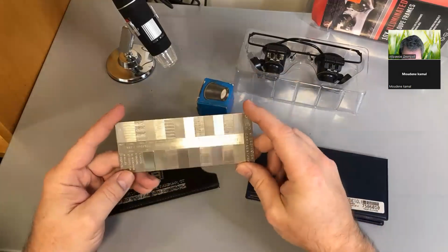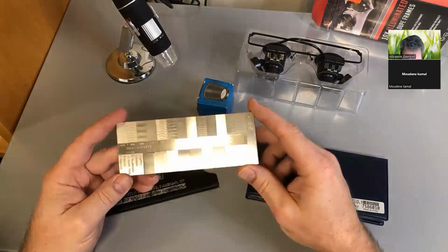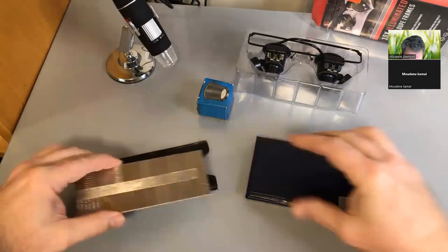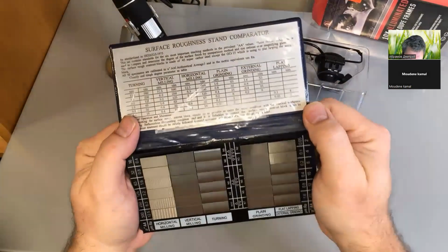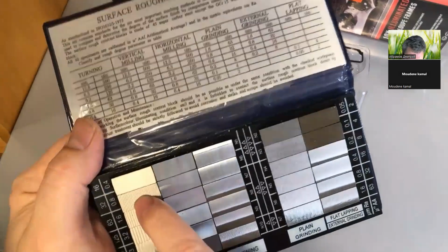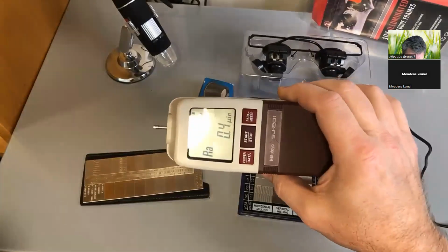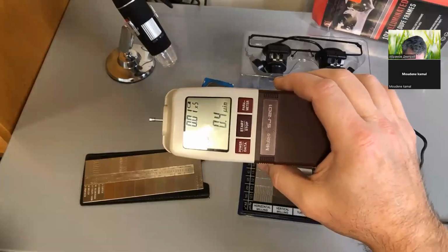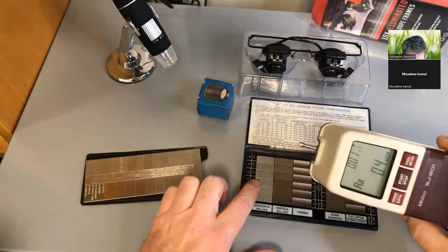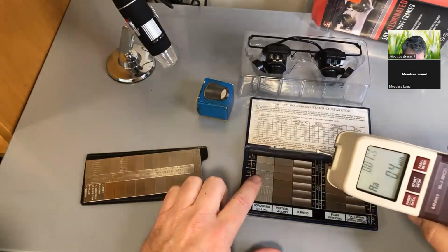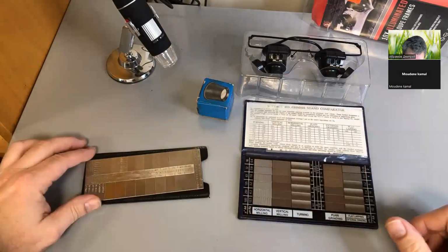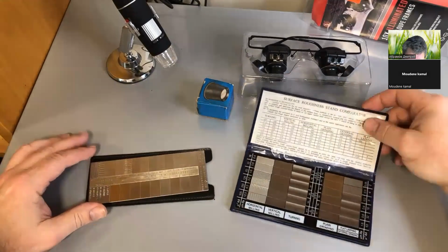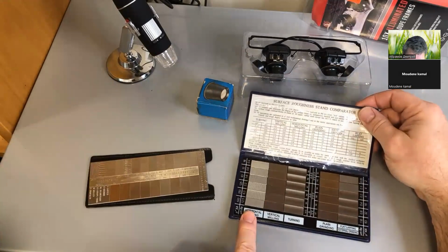Although this guy's nickel, because it's a nickel plated process, how they actually make these. This visual comparator here, if you look really closely right here, there's actually a hair stuck inside of this sample. How I know this is because I ran the surface roughness tester over top and I wasn't getting an accurate reading for what the actual specimen was saying. Now that doesn't mean that it's out, it just means that there's a slight coating on top of it to protect it. But the visualization works great for these guys.